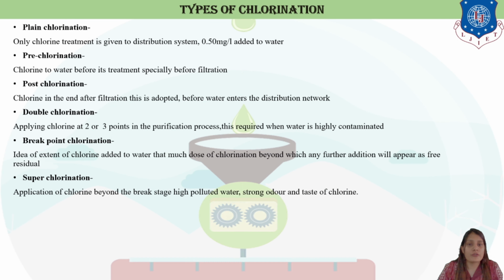The tablet of small ceramic disc is impregnated with silver or copper nanoparticles. Right? Similarly, Medidrop filters are used, which will remove impurities. The filters are made of local clay, sawdust, and water. This material is mixed and pressed into the mold and then fired in a kiln. So these materials are basically used to do the purification of water.